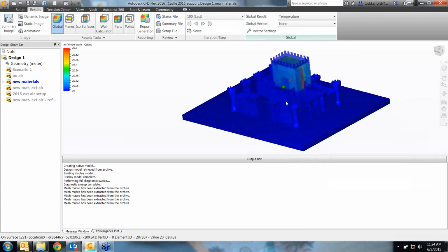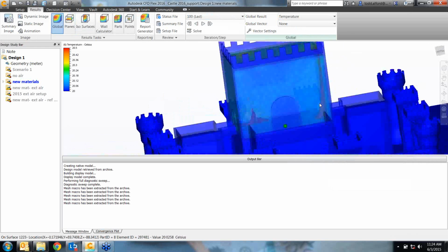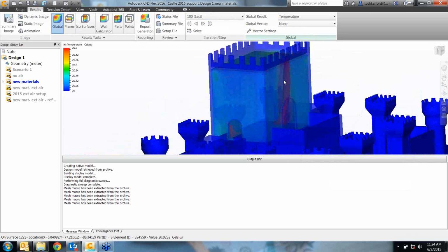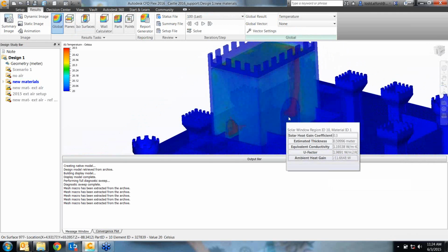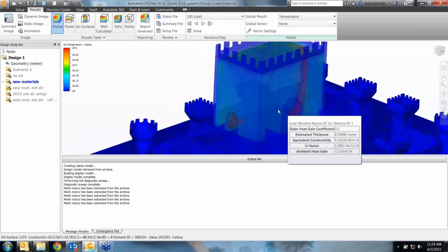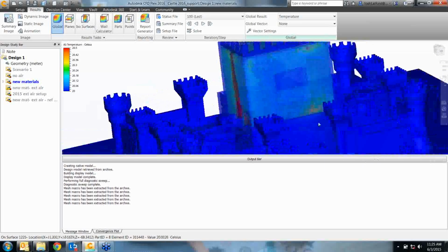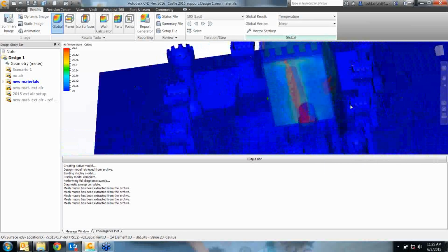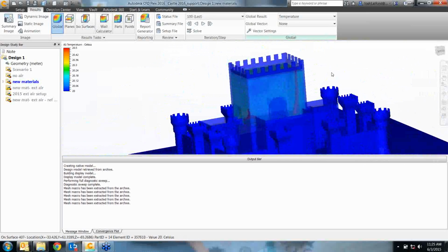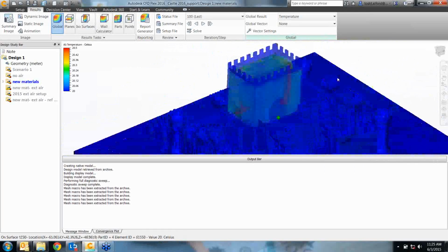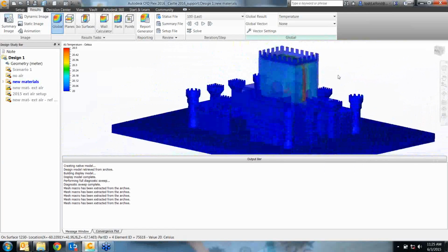This actually has a fairly poor mesh, but really all we're looking at is our top room, and you can see I've got an iso surface with temperature showing here. As I heat up the floor from the sun coming in through both the glass door over here and this window, I start to have some hot air rising and filling out. We have no real ventilation, so it just gets stuck in there. But I thought it was a fun model to show, just to give a reasonable representation of what can happen.